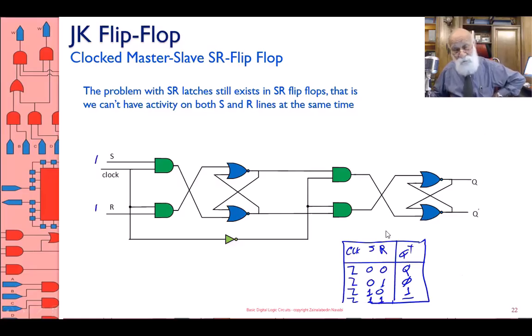So it's still better than the original SR latch, because it has the clock, it doesn't have transparency and all that, but then still has this 1-1 problem area that is right here, which we don't like. Let's see if we can resolve this issue. Let's see if we can still have something that sets and resets and is clocked and it doesn't have transparency.